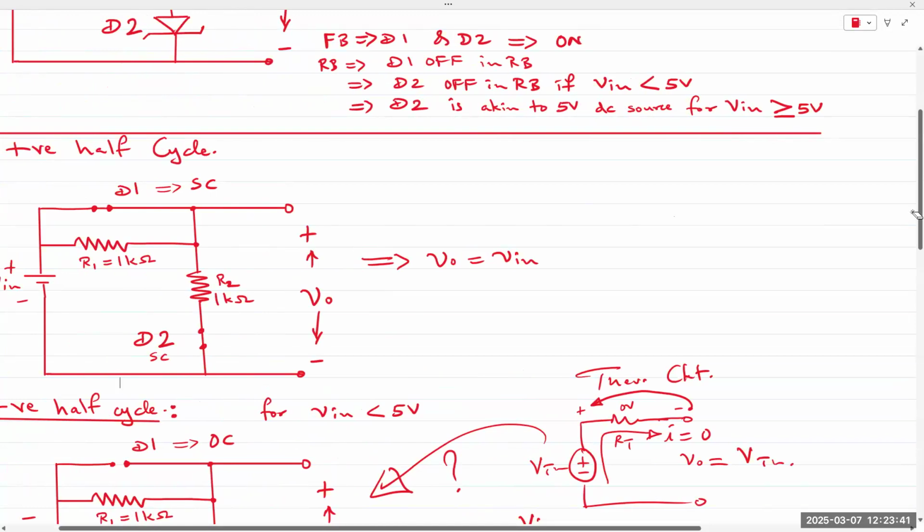Okay, so forward bias is all a short. Even in reverse bias, it's not going to turn on until it passes the 5 volts threshold voltage. So even until then, V out will be equal to V in. It's only afterwards that it drops.